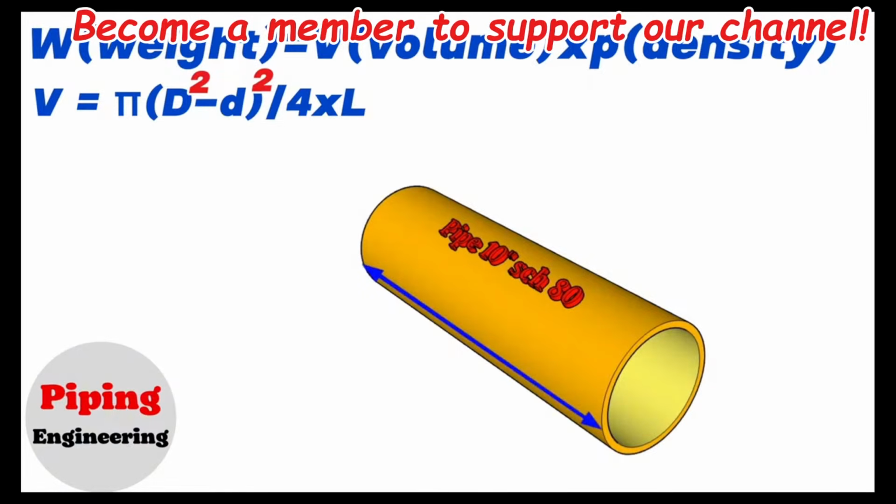To estimate the volume of the pipe piece, let's look at the wall thickness of a 10-inch schedule 80 pipe from the steel pipe dimension chart. This is the steel pipe dimension chart. The nominal pipe size is shown in the first column. The outside diameter of pipes is shown in the second column. The nominal wall thickness schedule is shown in this last column.